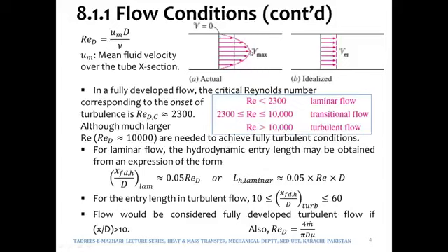So if we take the average of all those velocities, we would get a single average value of velocity, which we call the mean velocity, which we have represented over here. So instead of writing it as U infinity, because when the fluid is flowing at any cross section, its velocity will in fact not be U infinity, rather it will change from a velocity of 0 to a maximum velocity at the center line. Therefore, while the flow is taking place through a pipe, we make use of this representation of velocity, that we write as UM or VM, mean velocity.